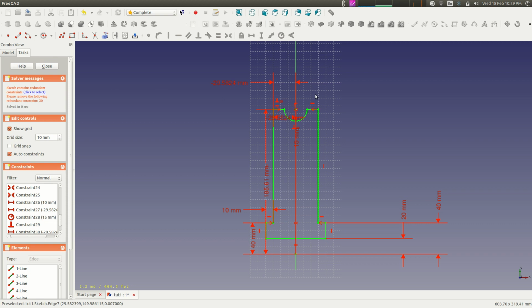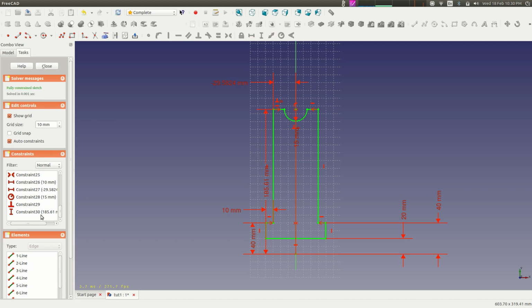And then as you can see, it found one of the constraints, but the problem with the lock method is a lot of the times it'll put in redundant constraints, but you just delete the redundant ones, and eventually, if every point here was locked, then the thing would be fully constrained. So a lot of them would be redundant and maybe even conflicting, but essentially that's one way you could go about it. The other way is just to click on stuff, move it around, and see which one. So the one that we were missing happened to be a height constraint, so I'll just maybe go back to where we were.